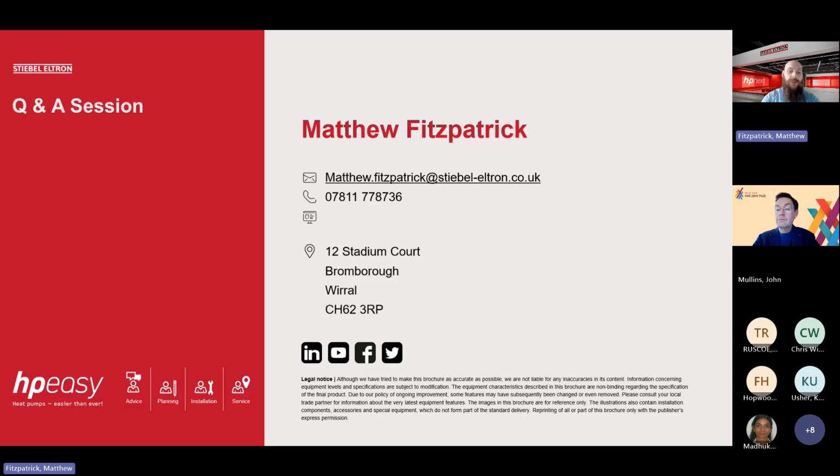That's where I would look and focus, because it's quite easy to take the cheaper initial cost and have one large unit, but you'll find during that heating season, that two thirds of the heating season, your single unit could be operating at 60% or 50% capacity, or maybe 70%, whereas two units would be operating at 30%. And it's a lot more efficient to do. And the more efficient the output is, the less you use to run that compressor, the less it's going to cost you. So that's how I would look at it.